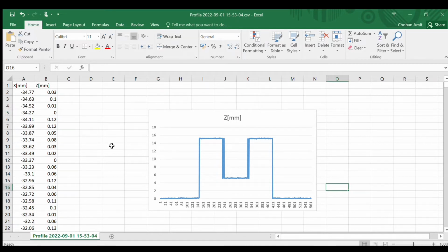Okay, so what we now have to do is add our third component, and of course you can do this via UDP streaming, via Modbus TCP, whatever you want to use to take that third axis from for the Y information to give you your 3D data from the encoder input. You have to make sure that they're synced in time so that your X and Z is being taken at the same time that we're taking the information of what Y value it is to give us that third dimension.